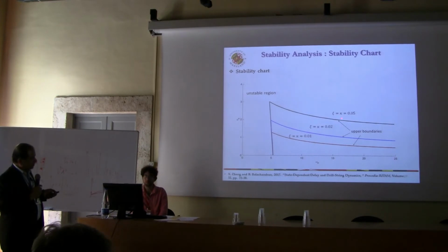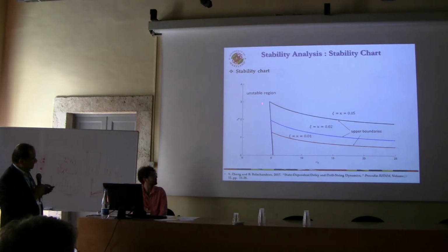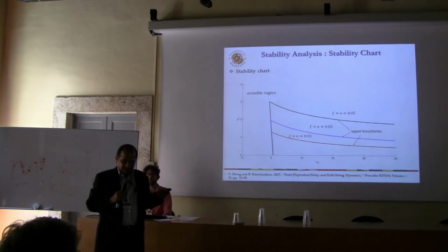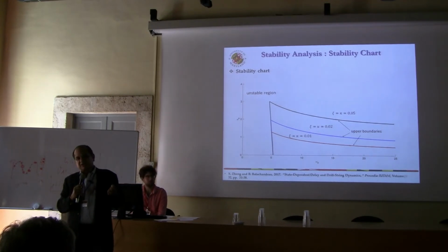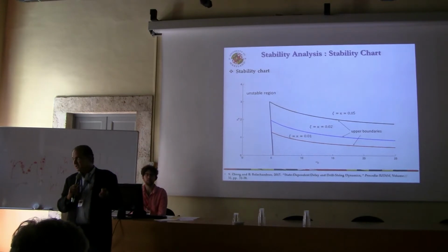Now, of course, if you decrease the value of damping, the region of stability decreases, so that's what you see out here. The state-dependent delay affects this particular top branch, and the constant delay affects this portion of your system. So again, the point being that with the consideration of state-dependent delay, you pick up the effects of the penetration speed on the stability of the system. Had I just done a constant delay model, I would have missed picking up that effect.